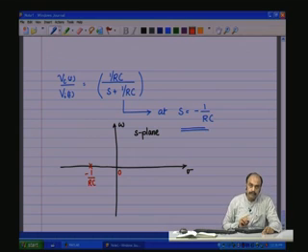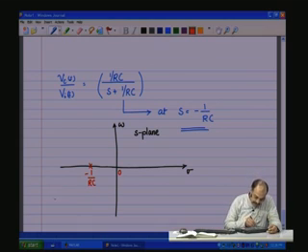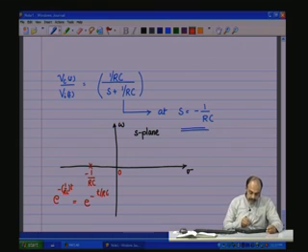So, what does it mean? It means that when I have any disturbance or any particular excitation and that excitation is removed, that excitation is going to decay as e to the power of minus t by R C. So, it is going to decay with a time constant of R C. That is what it means when you talk of a pole.